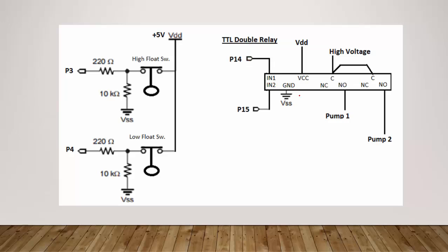And they will be controlling the two different relays that are on the same circuit board. So what we have to do is just take a jumper from the source and the common on this relay, bring it over to the other relay, and for pump 2. So not much of a difference in the wiring with the second pump.